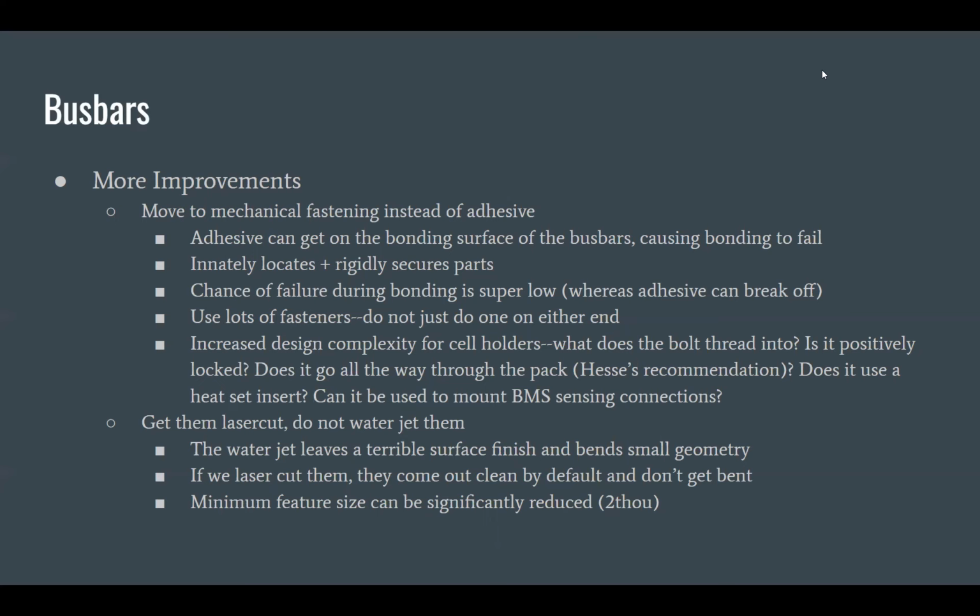They're like, yeah, that is the most effective way to do it, is that you just bolt through the whole pack and hold the bus bar on that way. That's the greatest way to do it, especially if you do a taper and a tapered bolt head, then it'll fully locate it more than something like a regular threaded bolt through a clearance hole would. So that also puts challenge.